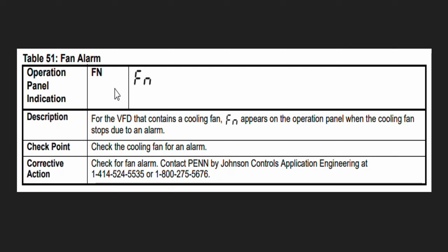For temporary purposes, you can use one external fan at this place. If you use an external fan, this alarm will be resolved. Normally it occurs when the temperature is higher than the limits, and it happens because of the fan. In some VFDs we have proper feedback of the fan.